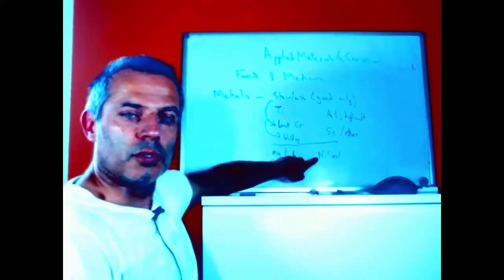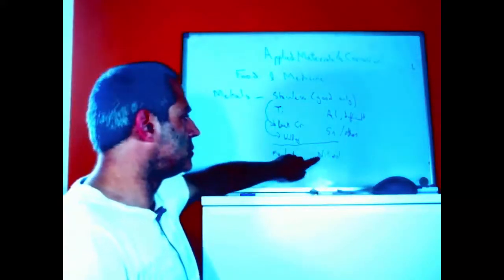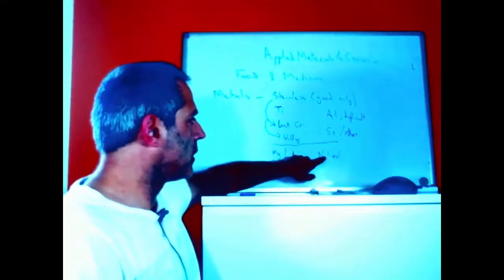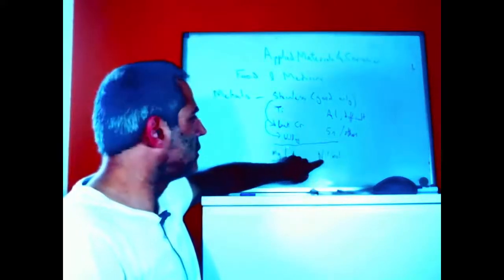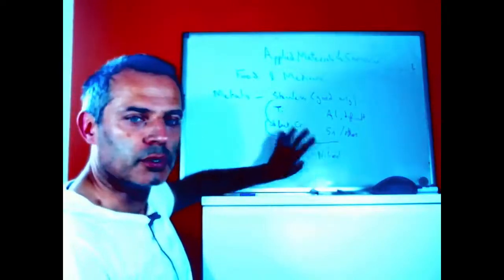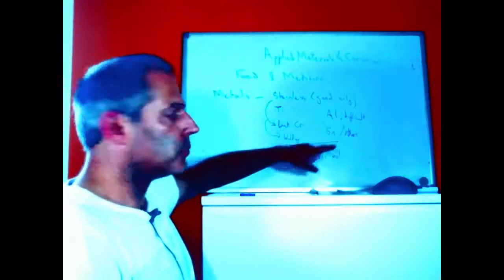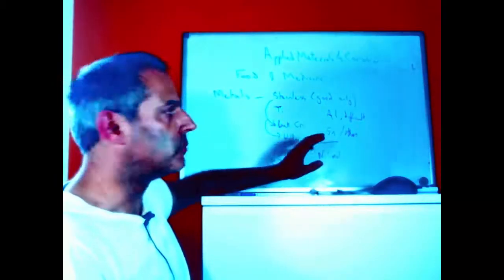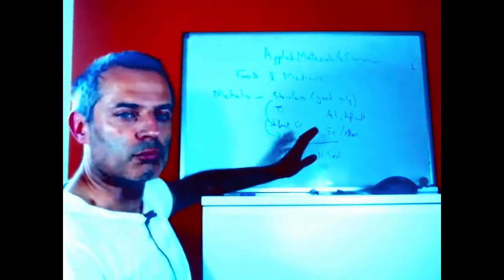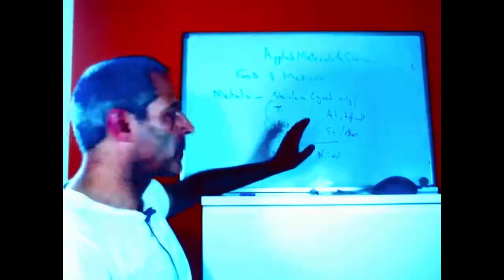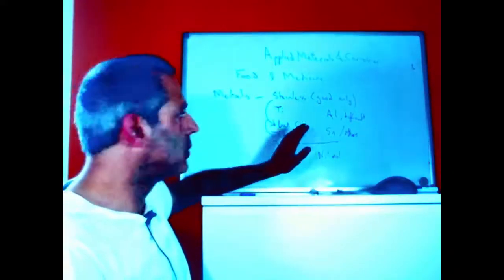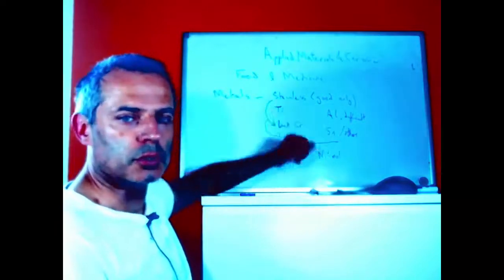Also nitinol, which you would think is not very suitable because it's a nickel titanium alloy. It is however stable enough that it can be implanted into the body, and the titanium oxide on the surface of it reduces the amount of corrosion enough that it is reasonably safe. It is also quite easy to sterilize because of the titanium oxide layer on the surface. Titanium is a good example.